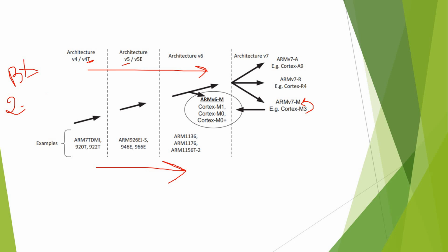On ARMv5, ARM extended this exchange capability to cover other instructions like BLX, branch with link and exchange. This instruction is used heavily within procedure calls. And within a procedure call, now we have the capability to trigger the CPU state exchange between ARM state and Thumb state. Other instructions like LDR, LDM, and POP, which can be used to load and update the program counter from stack or memory, have the capability as well to exchange the CPU state from ARM to Thumb or from Thumb to ARM.